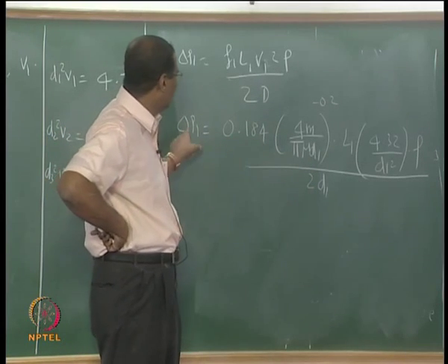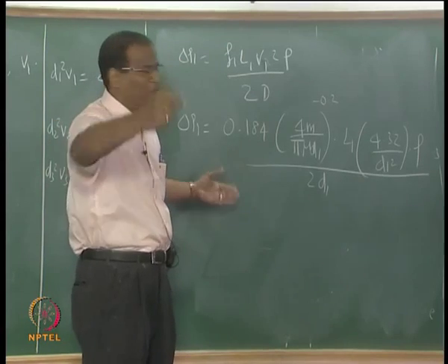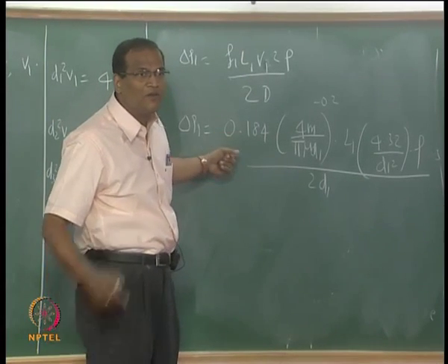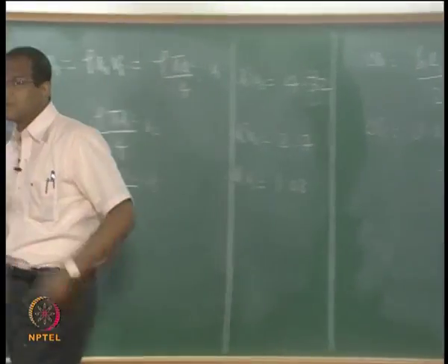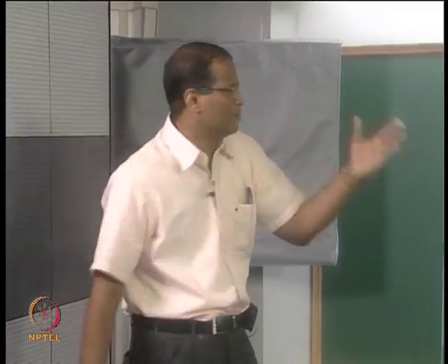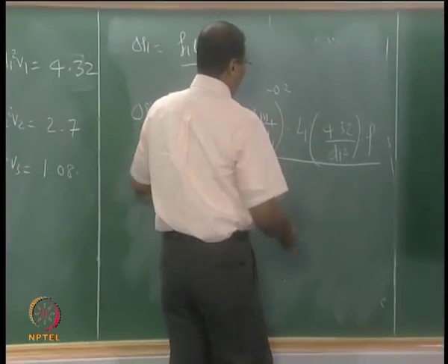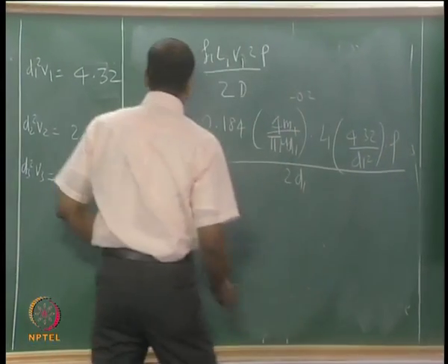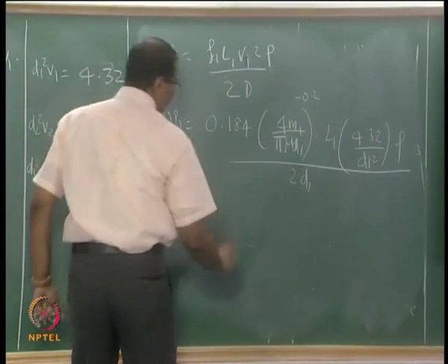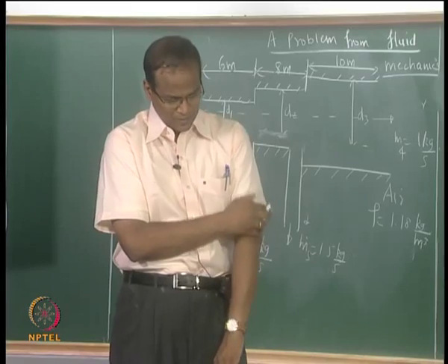Now you can see that delta P goes as d to the power, this is what is solved for the pipe, and for your assignment 1, d goes as minus 4.8, that you should never forget. Then you can assemble all the other things and put it as a constant. Can you tell me, you know all the other values, m1, L1, rho, everything, so delta P1 is equal to 982 by d1 power 4.8.